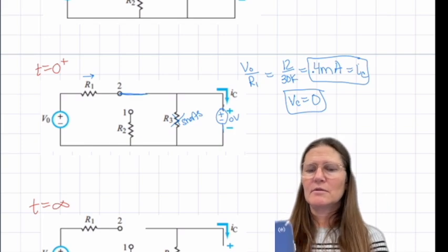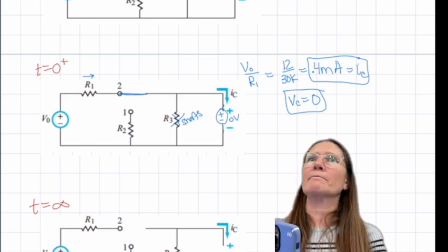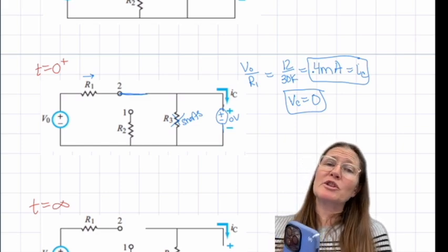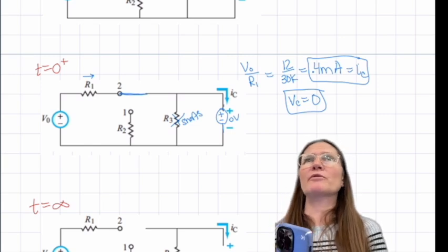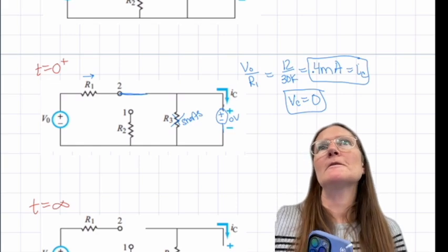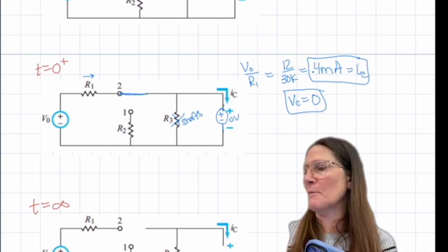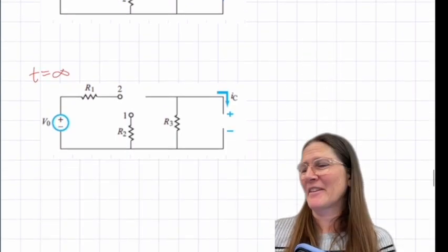Yes. Do you want us finding the current using a 0 plus time, or can we take, once we get that final equation, the voltage over time, we just take that directly? Yep. So if you find the voltage and not go through these steps of finding it as you go for IC, that's fine. You can do C dV/dt and get the current IC. And it would be the same. It should be the same.